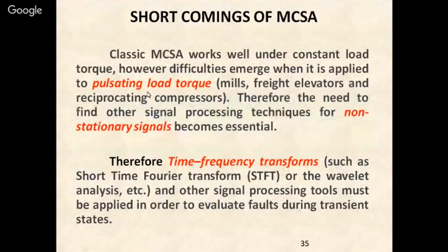One is that if we have a pulsating load, that means the load is non-stationary, then the current of the motor will be varying over time. So it will produce some non-stationary signals in the motor current, and we will have no sharp peaks like this. We will have a very blurred spectrum of the motor. So in that case, we have to apply some time frequency transformations like STFT, wavelet, etc., so that we can process the signal. Okay.